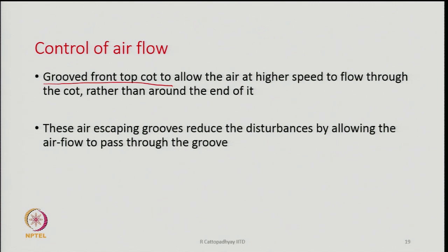The top cots on the front top roller have grooves on their surface, and these grooves allow the air at higher speed to flow through the cot, because where the groove is located the nip is not there. So, there is a passage for the air to pass through.